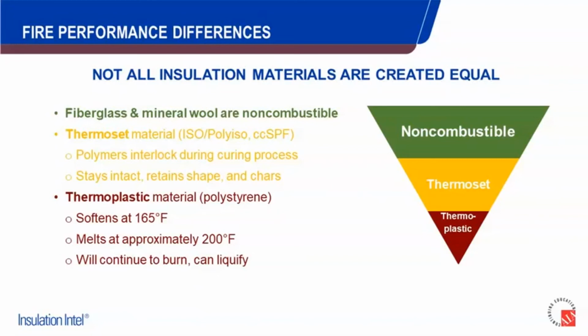You're going to find metal panel approvals, of course, and fiber cement. Metal panel was the unicorn approval for a while, in that it was a very difficult system to get past. We've seen quite a few assemblies over the last couple of years, and I would say it's becoming less and less of a challenge to find NFPA 285 compliant systems that include metal panel. So you will find metal panel approvals with your polyisos.